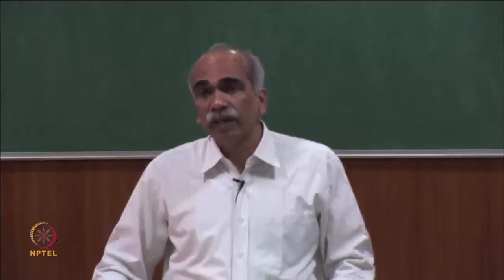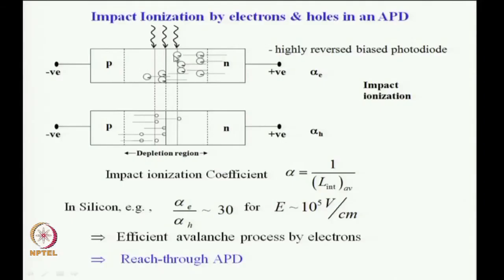When the electric field magnitude is the same, they gain much higher velocity, and therefore much higher kinetic energy, and lead to a rapid avalanche of further carriers. Holes get accelerated to the other end, and as they proceed, whenever they gain sufficient energy, they also generate additional electron hole pairs, and the holes continue to proceed towards the negative end, that is the p end.